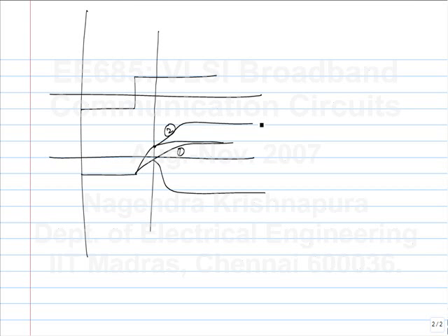Does it have any effect at all? Yeah, that's true. Of course, GMR should be greater than 1. But once it's greater than 1, does it matter whether it is some particular value or something else? Okay. So you are saying you should use the smallest transistor. Okay, GMR is 1.01. So where would you size it? Okay, let's say we design it. We have designed the latch so that it regenerates within the half clock cycle that we want.